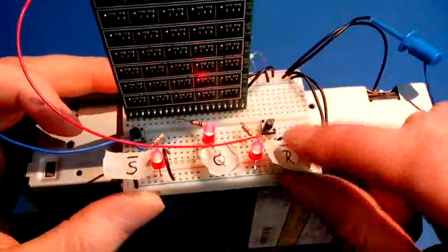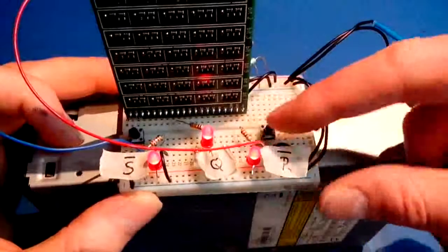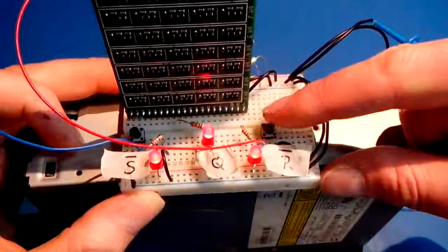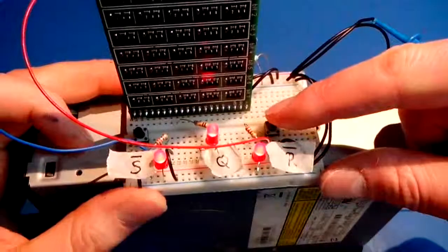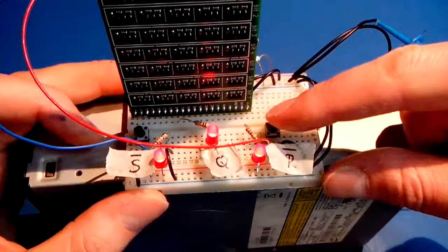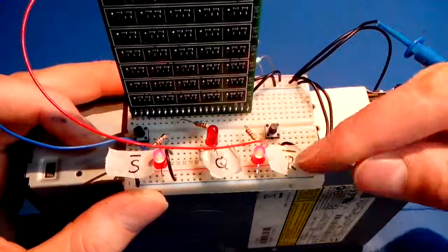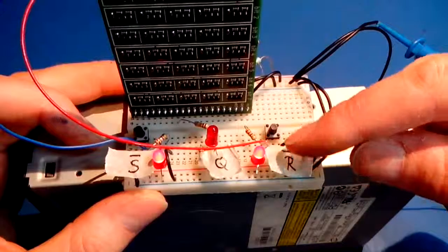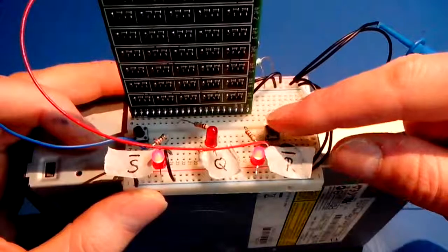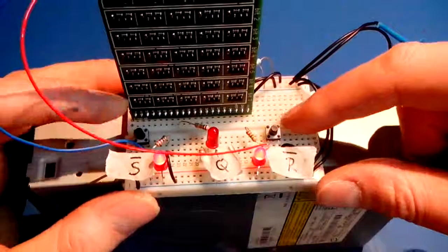Right, so now we have a push button to control the input R over bar of the set reset latch. Pushing it will apply a low voltage at the R over bar input. In other words, will activate the R over bar input. In other words, will reset the set reset latch. Actually, we just saw that already.